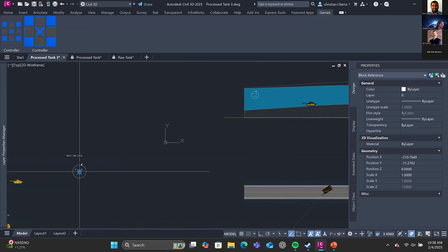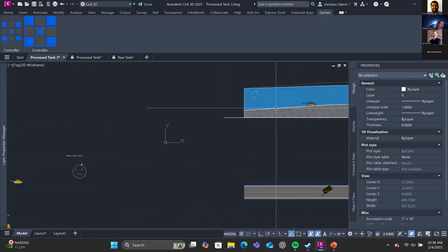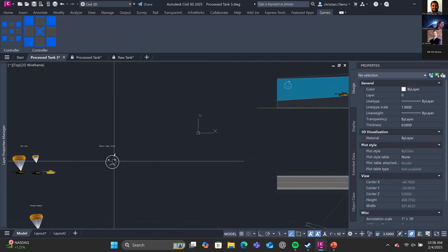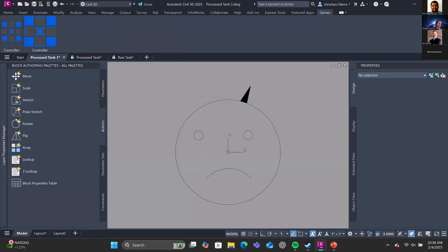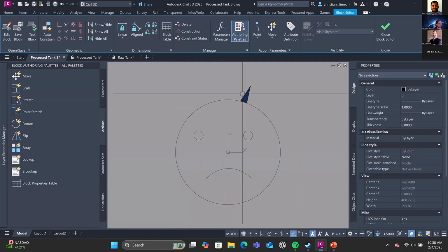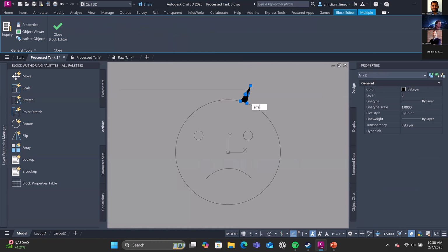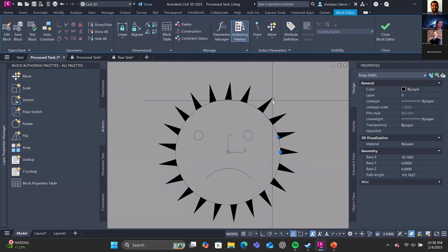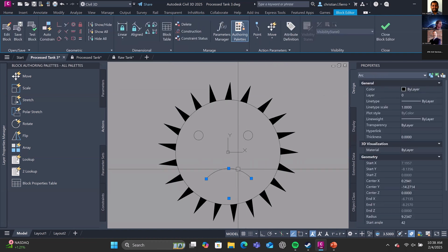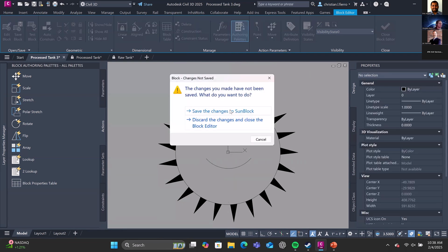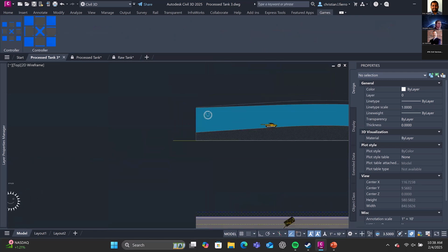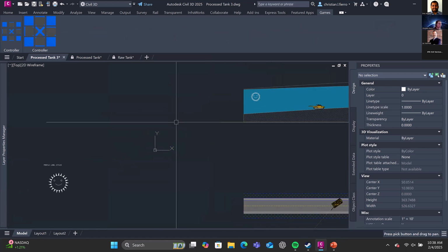So looking through here, if we have a label style that is using a block, this label style is using the reference of this block here. So we can easily have this practice to make some very simple modifications along here. And then this will update all of the corresponding label styles with this block. So if we have any refinements at all, we can always do that.